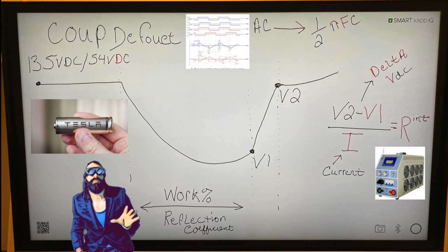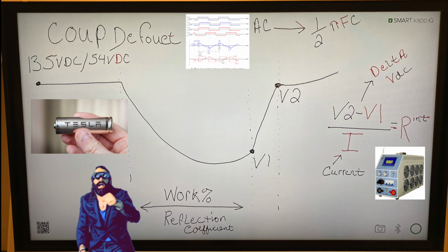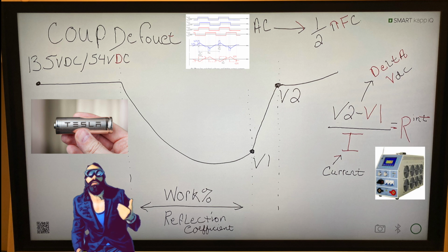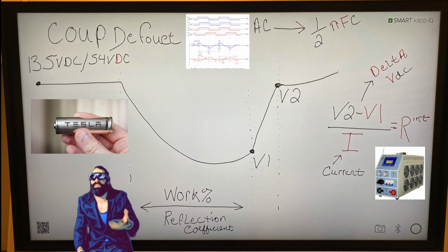Now, in battery systems in general, we also look at inter-tier resistances and intercell resistances. Same methodology, we're looking at the voltage drop across the cable, 100 millivolts, 200 millivolts, 300 millivolts, et cetera, et cetera. The inter-tiers are generally the cables that go from rack to rack or tray to tray in a cabinet system. You might have 10 different trays of 4 batteries per tray, and we need to measure those resistances accordingly, because also under a discharge, we have to add that voltage drop back to the cell input channel. Otherwise, you would see, every 4th or 5th battery, 80 to 100 millivolts low, and it will look like they were degraded batteries.